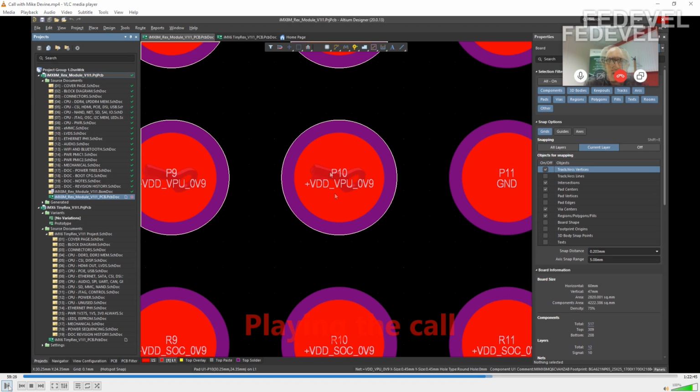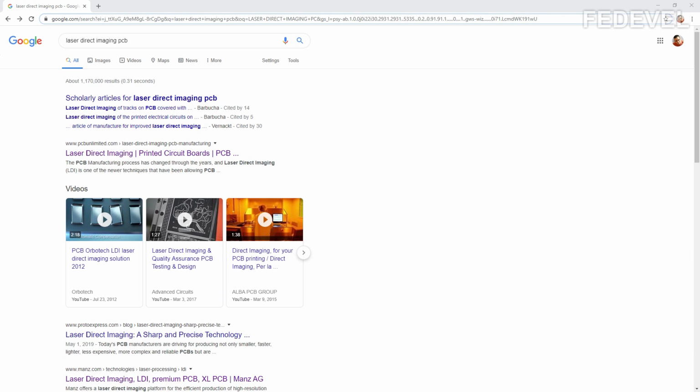So it's not only position, they also have visual aid. Yeah, correct. We only use lasers now, so even all our imaging for print and etch of internal layers is done with LDI, laser direct imaging, no artworks, because we take out the stretch and the shrinkage of an artwork when it gets warm in sunny weather and cold in the winter time, and it reduces defects as well. So if there were any marks on the artworks, that would get superimposed onto the image. So yeah, it's all done with lasers now. I googled for laser direct imaging, so you don't have to, and this is what I found.